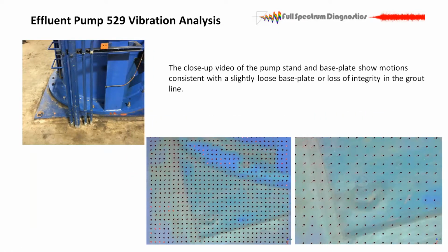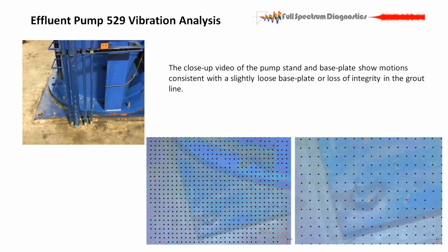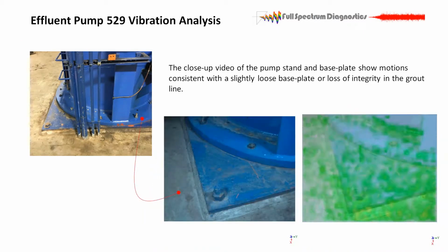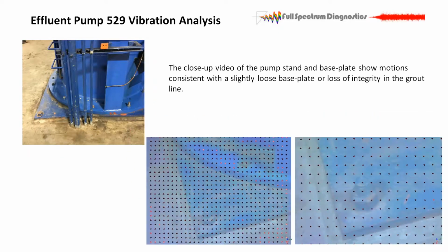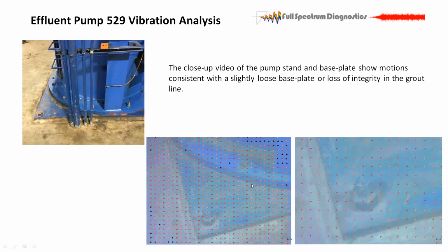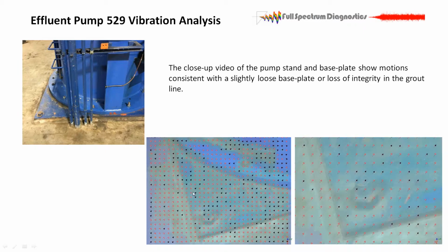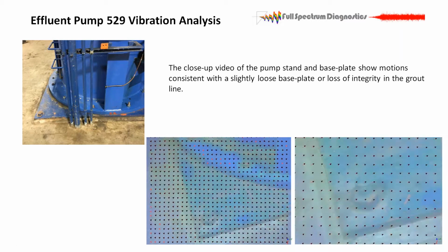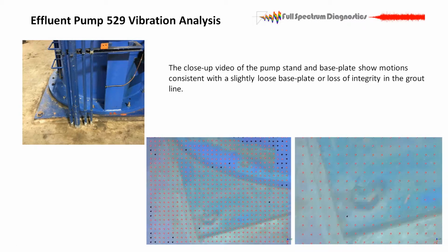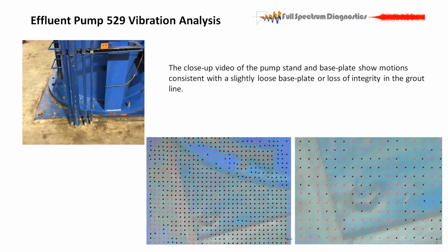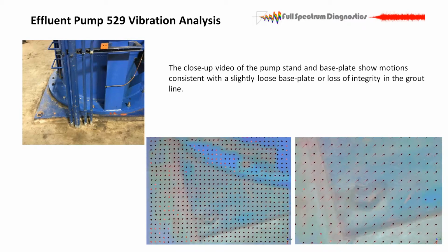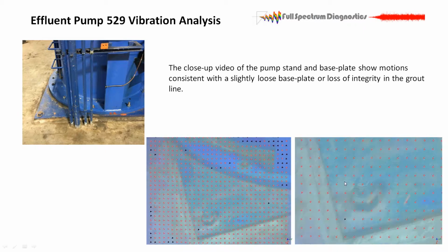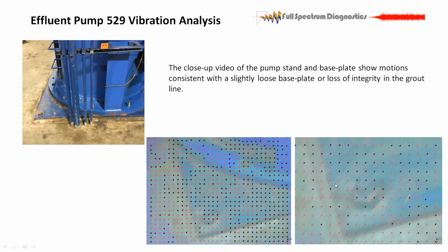This is optical flow. This is the intensity vectors all over the structure. So the same motion from before, it's my same image. I left the color contour on and I lit up the vectors. And you can see how they're changing direction and they're stretching a little bit. So what happens in this type of video, there's a flow of motion from that time waveform at each pixel, and the direction is coming directly from whatever the camera orientation is. If I zoom in on that a little bit, you can see how all the vectors are turning direction and stretching at the same time.